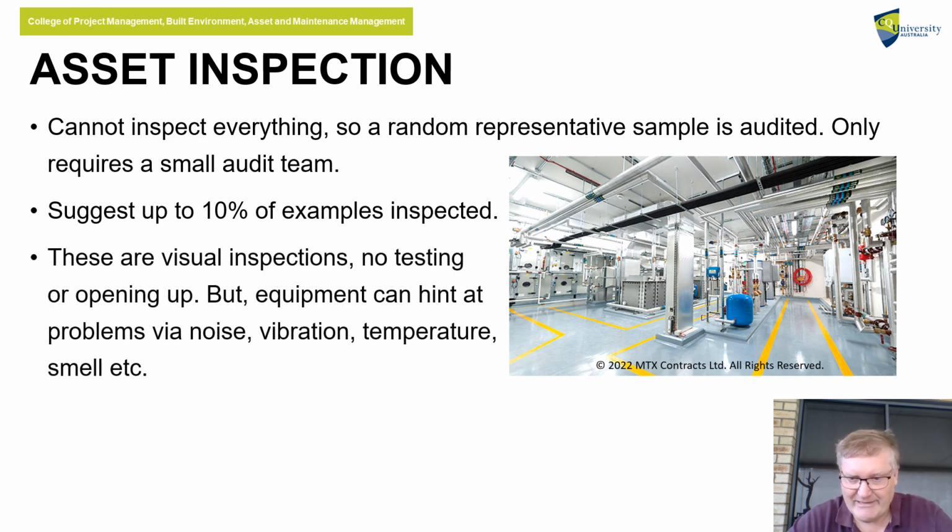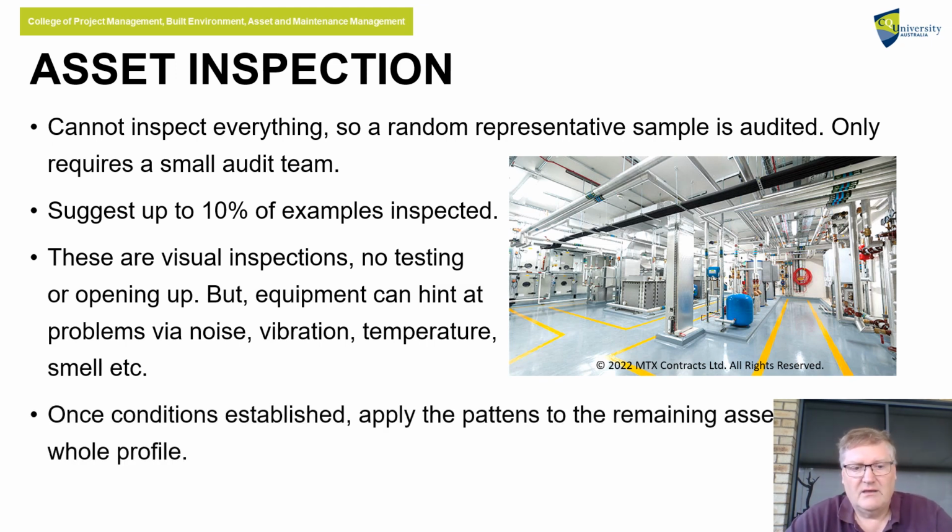You're not going to test anything. You're not going to open up any cupboards or make holes or dig holes in the ground to look at things. You're just going to look at them and take a photograph of them. But the equipment itself can give you clues that something's wrong. It could be very noisy, or it could be vibrating, which would go with noise as well. It could be running at a high temperature. Quite often I've walked into plant rooms and I can smell burning oil. So you try to track down where that's coming from, because your bearings are burning out and things like that.